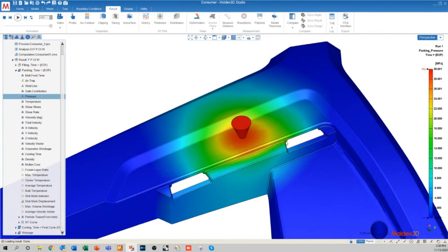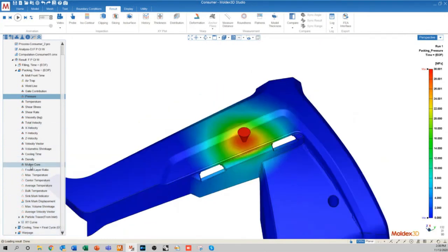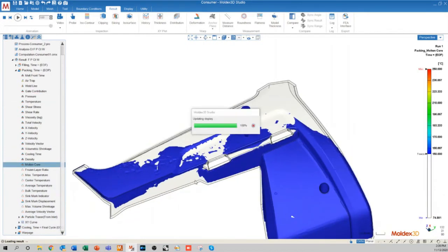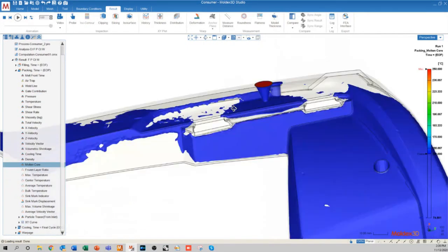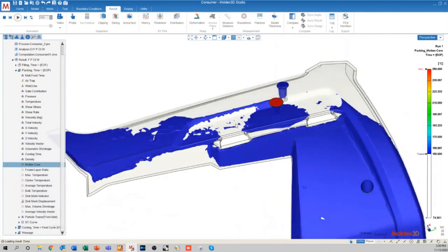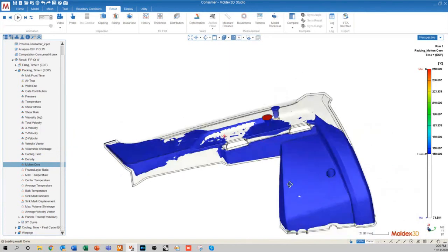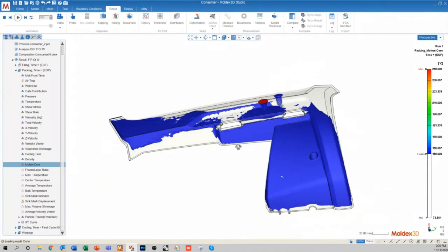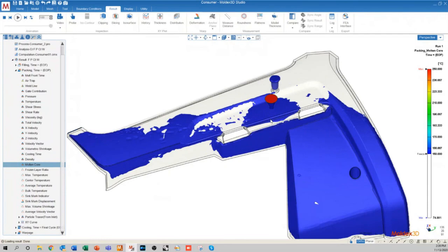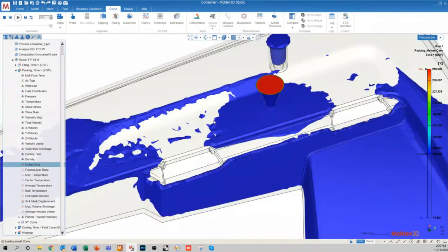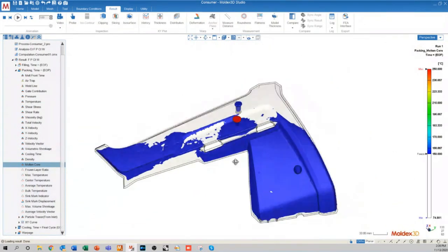So this pressure application, we definitely want to identify it, and we want to fix this if at all possible. Usually this sort of phenomenon specifically that we're seeing in this part geometry can be fixed by just either slowing down our fill, reducing the amount of shear that happens. Maybe I can even increase my melt temperature to make the melt temperature a little bit more uniform throughout my part geometry. So this all kind of stems from the filling stage. And you can kind of create a DOE for yourself if you wanted to fix this.